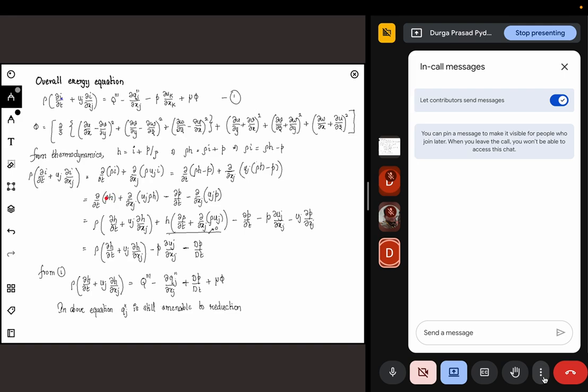One concerning, like you can take the density out, then you have an enthalpy term, and you can take the density in, then you'll have the continuity equation coming back, which is equal to zero because the continuity equation gets satisfied. And then you have some pressure terms. So if we condense them together, we have an enthalpy term followed by two pressure terms. And if you substitute them back into our original equation, this is the final equation we have here.